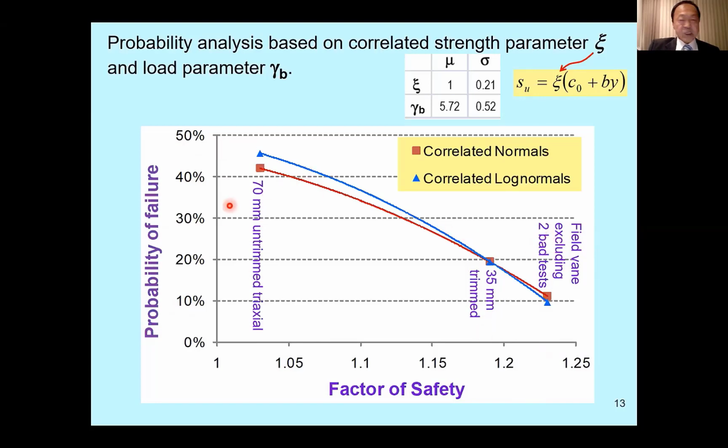In reliability-based design, for the ultimate limit state such as stability issues, we would like to keep the probability of failure below 1%, which corresponds to a reliability index greater than 2.5. Therefore, these three values of probability of failure all imply that the reliability index is smaller than 2.5, therefore an unacceptably high probability of failure. And no wonder a section of the slope actually failed.